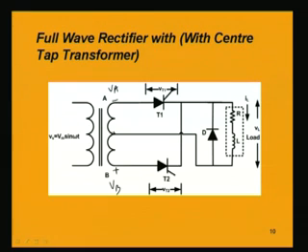So, what will happen is that the diode, if we look into the diode D, then this N is negative with respect to this P, and this means it is forward biased. So, as soon as VA enters the negative half cycle, the diode D will be forward biased.